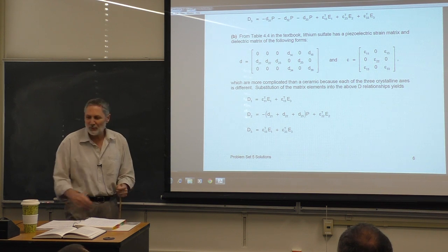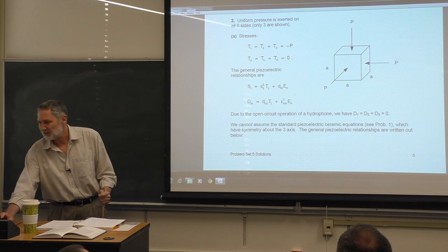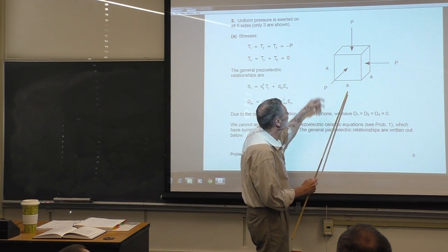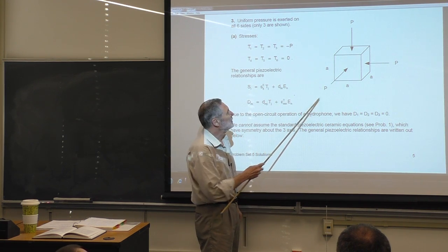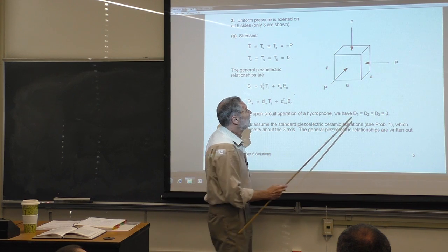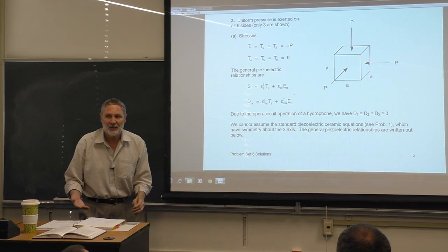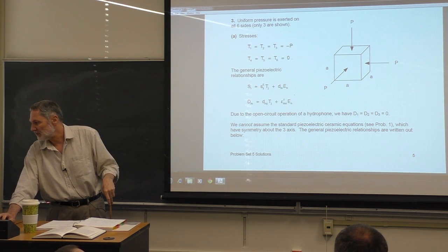Okay, so do you want to electrode and attach the leads in the 1 or the 3 direction? Let's see, I didn't label it here, but I guess this is the 1 direction. This is always the 3, and that's the 2. So do you want to put electrodes in the 1 or the 3 direction? It would be pointless. There's no electric field. You won't pick up a voltage. So we have no choice here.